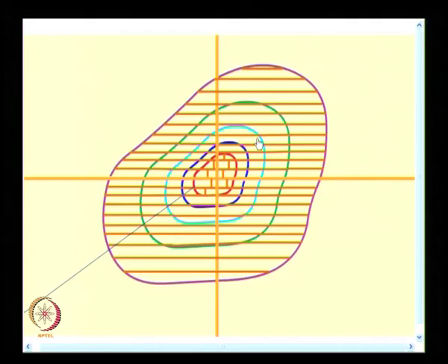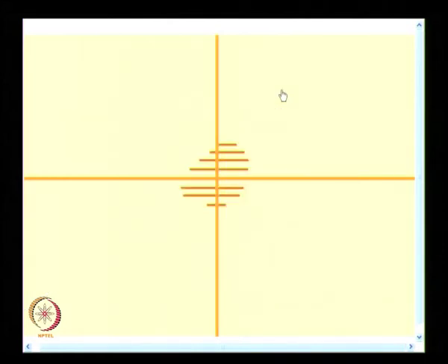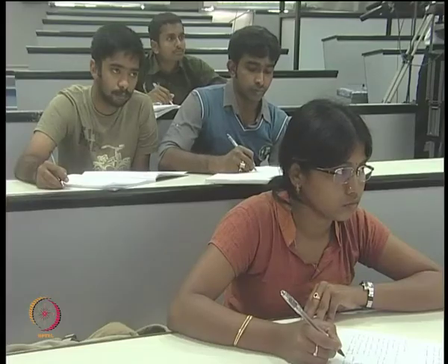So, when you want to look at brittle coating, what you will have to look at is these isostatic patterns. You have to mark them, and use these patterns to find out the quantitative value of stresses. On the other hand, if I combine brittle coating and strain gauges, I have a lot of advantage. The advantage is, I know the principal stress direction from the isostatics. So, I can align the strain gauge appropriately on an actual test component.